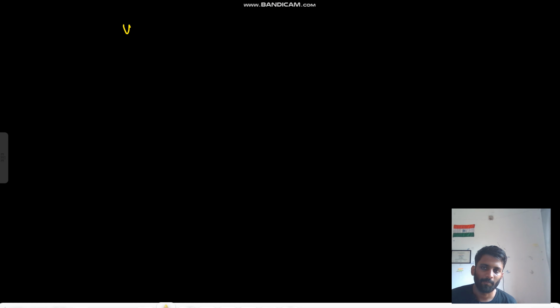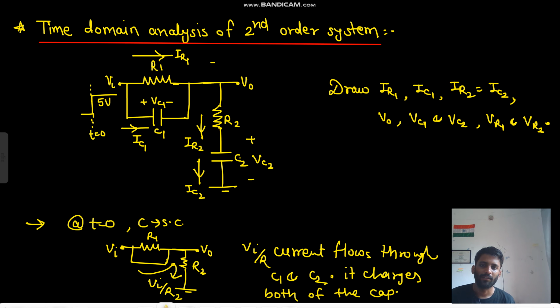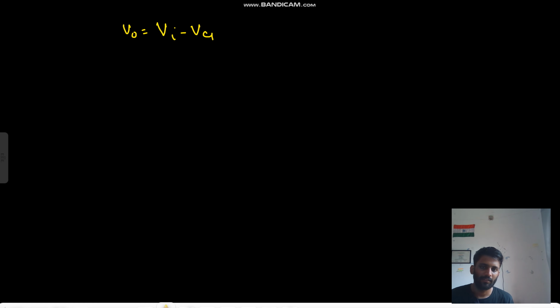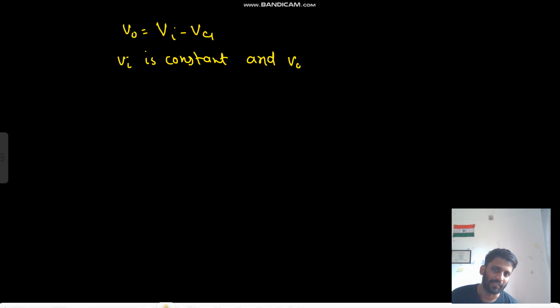what is your V naught? Your V naught is V in minus Vc1. Okay, V in is constant and Vc1 is increasing. Vc1 is increasing, so because of that your V0 goes down.